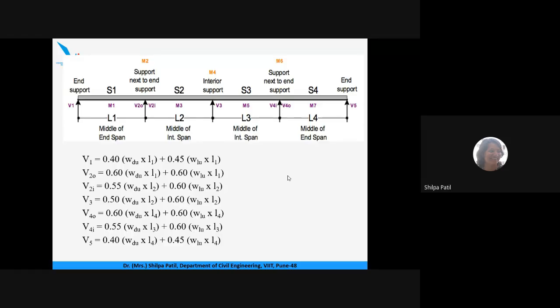Then we will come to the end, we will find out the total moment, then we have to draw the diagram again, and we have to analyze each and every span separately to find out the shear forces, and then we calculate the final shear force values and final bending moment values. That too again, support moment we have to calculate separately based on SFD, and span moments we get only from the moment distribution method. So that is a lengthy process.